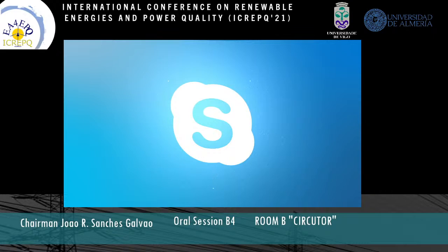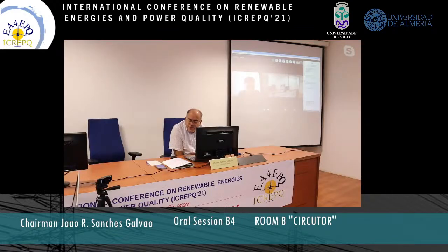Actually, there is a part of my work where I consider the electromagnetic and power electronic interface used to connect the wind turbine to the grid. One of my research topics includes considering multi-level inverters to do so. I think that 3-level cascaded H-bridge inverters are very good to use for this precise scale of wind turbine, starting from 1 megawatt.